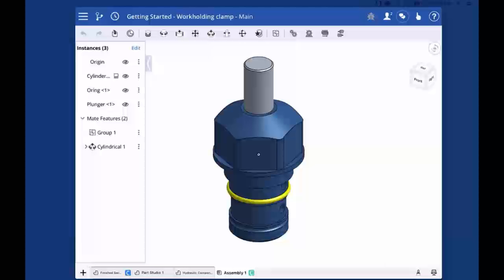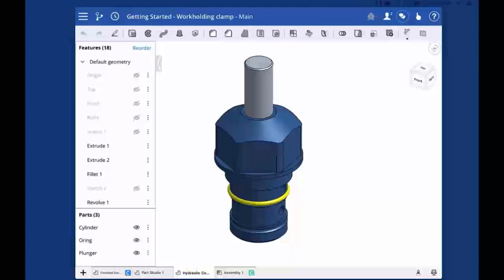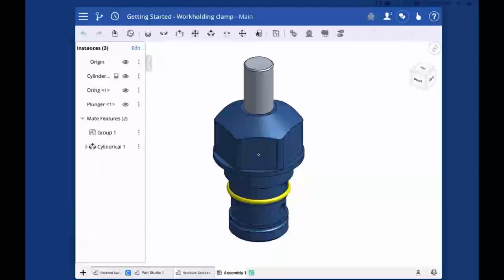But an important thing to point out, if all you're doing is building a static bunch of parts, for example, you can build parts together in a part studio. So it's an important thing to point out. Assemblies in Onshape are really about motion. In this case, you'll see I've modeled 3 parts of this hydraulic clamp together in the same part studio. So just realize that's an option as well. You can build as many parts in a single tab as you'd like. But assemblies are all about testing and fitting, motion, making sure I don't have collisions and things like that. So let's get into that.